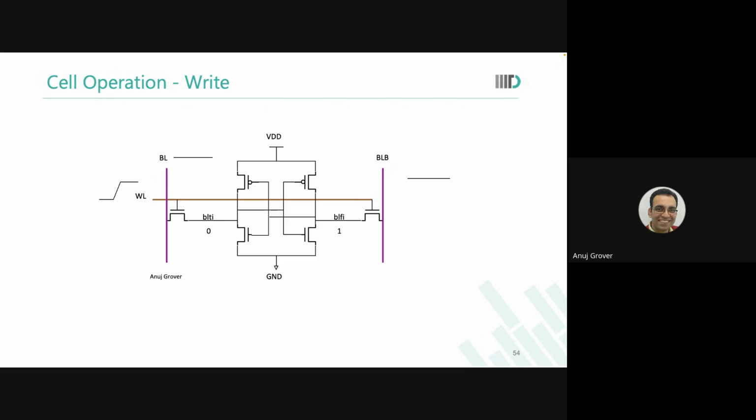If they are not able to generate VDD minus VT, they will say, no, this design is not possible. Or, I can generate VDD minus VT, but then you have to give this much area. Are you ready to give that kind of area? Then you will think, oh, I wanted VDD minus VT to reduce my memory cell area by 0.1. But the circuit that this guy is proposing will effectively increase the memory area by 0.2.